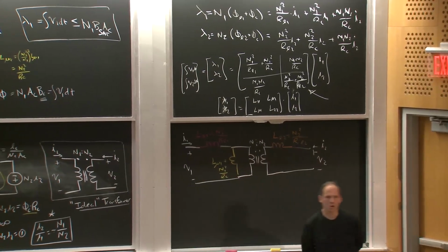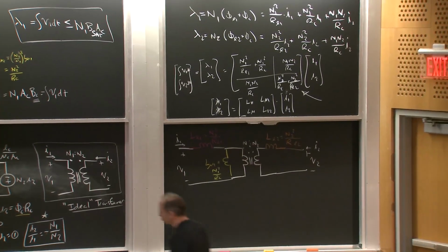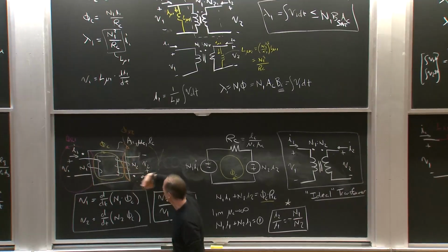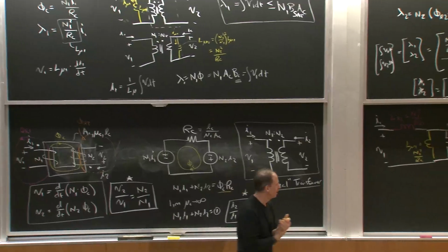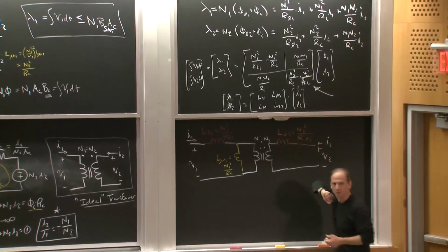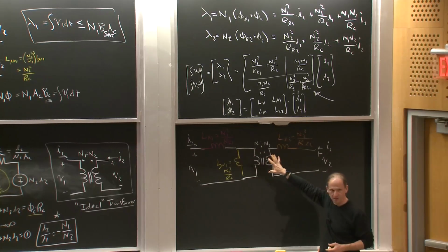Okay? So all that happens, if I include the fact that in this drawing there's some additional leakage flux paths that go out of the area that I ideally would have, is that I get two independent inductors here that get added on to my full transformer model.